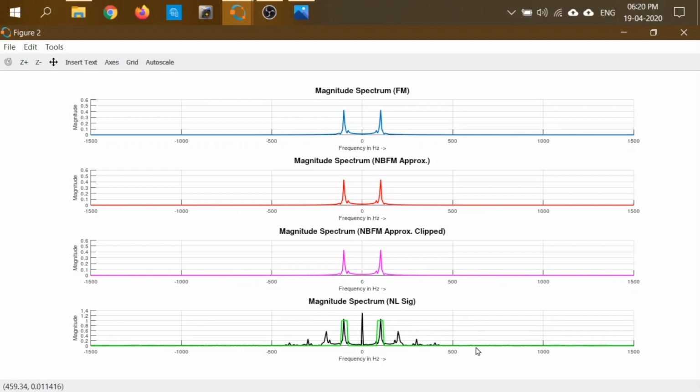So these things are there up to the point of the nonlinearity order. Meaning if I have a sixth order nonlinear system, then we will have components till 6 times omega c here, right? And suppose I want to have a signal which is shifted from this particular omega c to twice omega c, I can just put the band pass filter here. This green one is the band pass filter which I have kept, to begin with, at the original position of omega c.